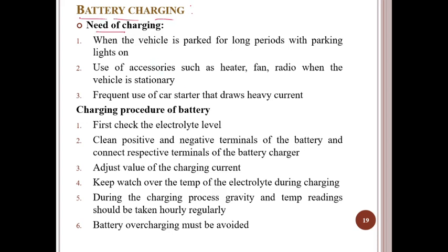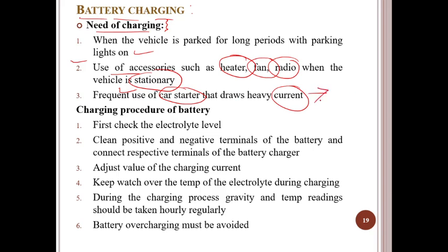Why is charging needed? Why charge a battery? When a vehicle is parked for a long period with the parking lights on, we require charging for that purpose. Second, when accessories such as the heater, fan or radio are used while the vehicle is stationary, we require more battery. And frequent use of the car starter draws heavy current, because whenever we start our automobile we require a very huge amount of current from the battery.